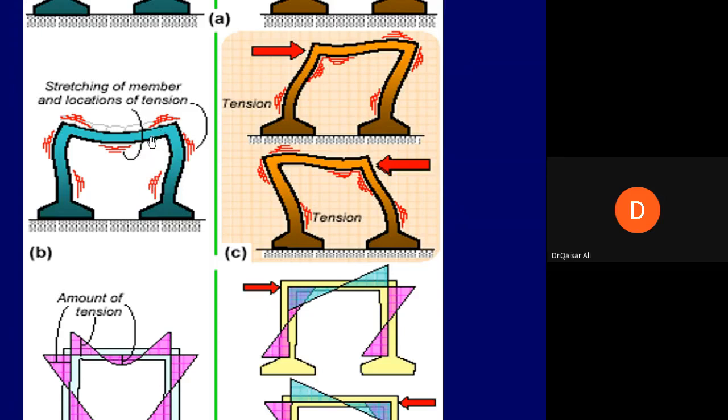These are not additional, because previously there was no bending moment here at the ends of the beam on the bottom side. So you will have new bending moments on the bottom side of the beam at the ends of the beams, and additional bending moments on the top side of the beam at the ends of the beams. Correct? And at the mid-span, there will be no change in the bending moments for beams, and at mid-height of the column. Okay.